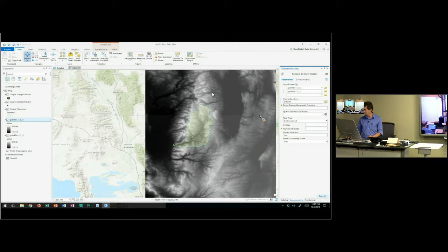I happen to know that this is a 32-bit float. If you were uncertain what to put there, you could look at the properties of these rasters that you're merging to pick something consistent. I also happen to know that there is one band. You could also see that in the properties there, and I've got screenshots of the properties in the exercise.